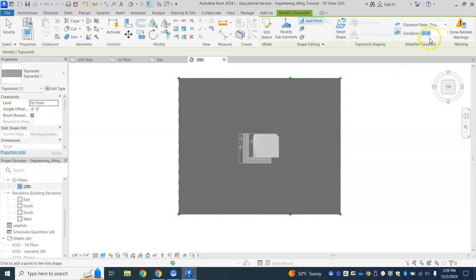Then I'm going to make one that's 1 foot. So just type 1 and it knows what I want to do. So I can put a 1 here. I don't need to click all these points. I can just see the edges, but I did. Then we're going to go to 3 feet, and let's do a 3 foot right there. We'll put one at the edge here, 3 feet there. And then I'm going to do one more, at 8 feet. So I'm going to click this at 8 feet there, at 8 feet here. And it looks like we need to make a couple in the middle to finish this out so that I kind of have this hill going on here.